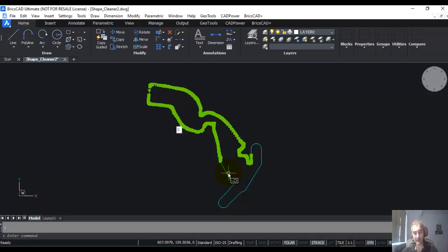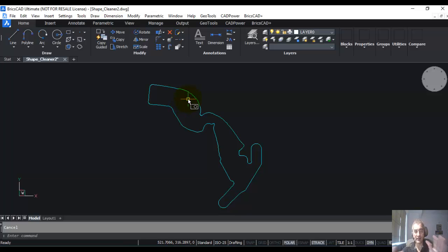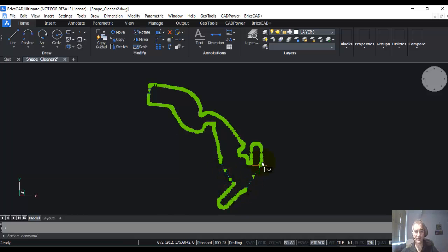You can see that it has joined more segments than before. So from a drawing which was really bad, which had a lot of duplicates, overshoots and mistakes, now we are ending up with a drawing which just has 5 or 6 segments. Now this is not difficult to manually process. You can just use the pedit join command and join this and get your clean geometry of a closed polyline.